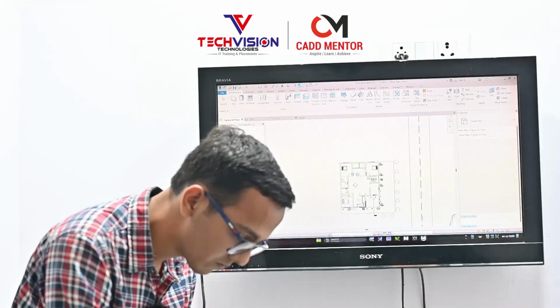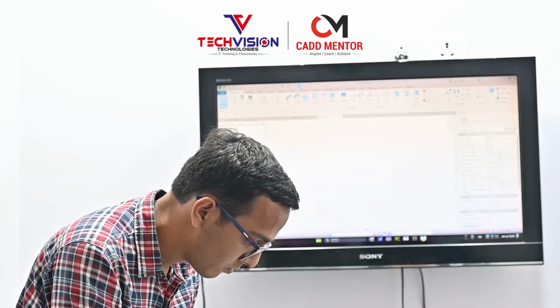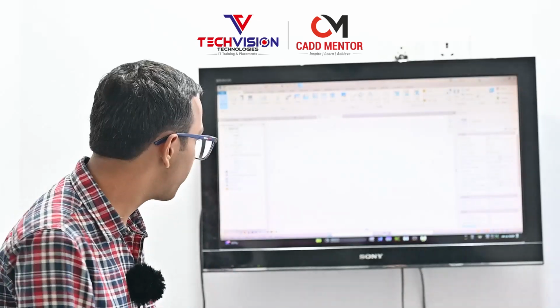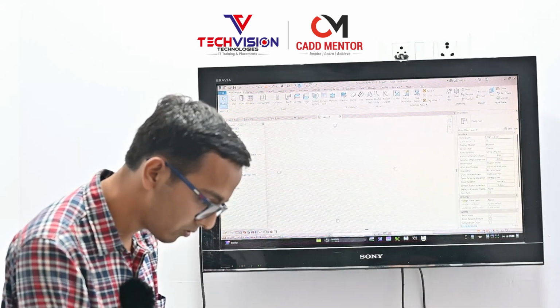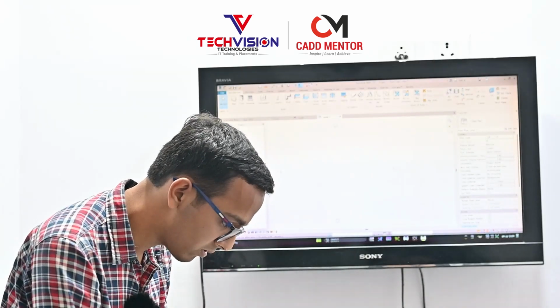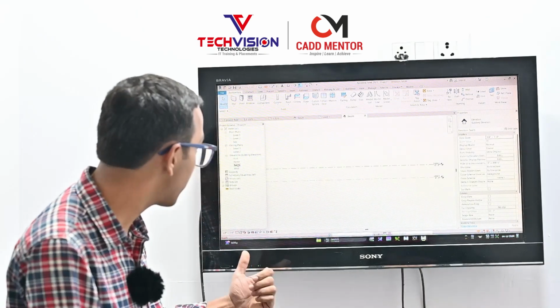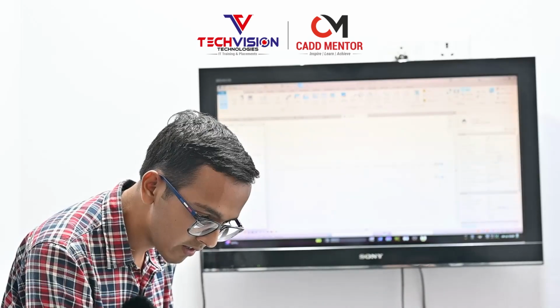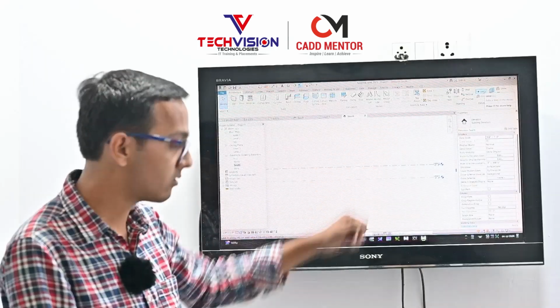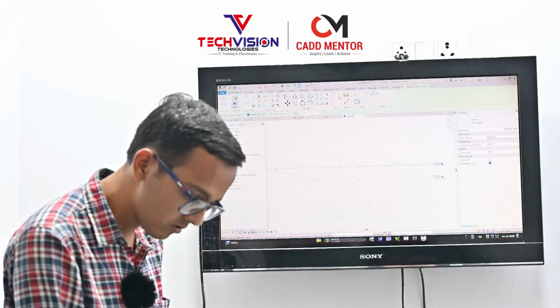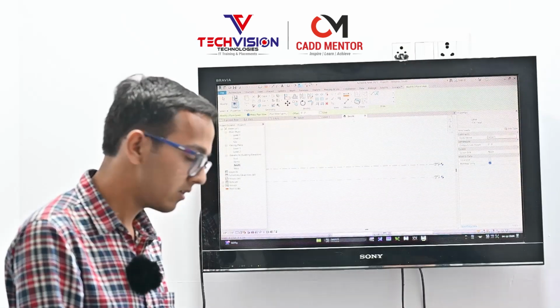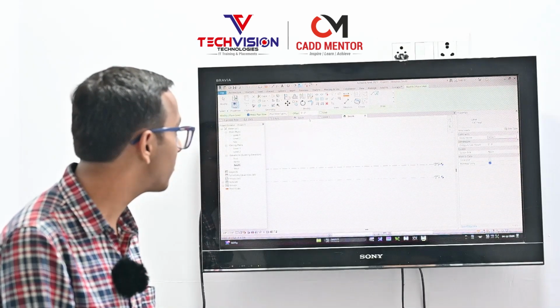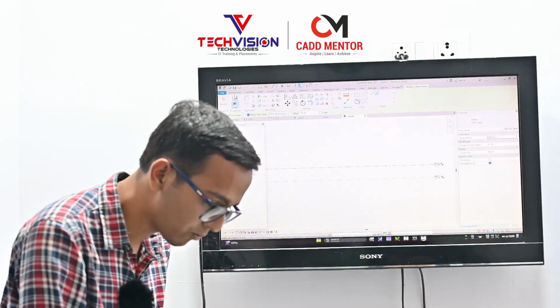And you can see the first page of this software. So first of all we should select the levels. For this you should go to the elevations, from the south elevation, and then select the levels. You can see the option Levels, and here you select this, and first of all take out the pick line so that you can see how much offset you want to give in the project.